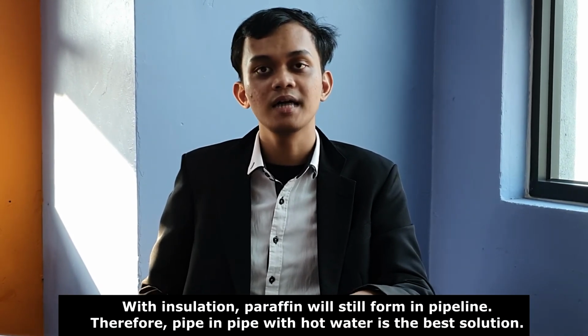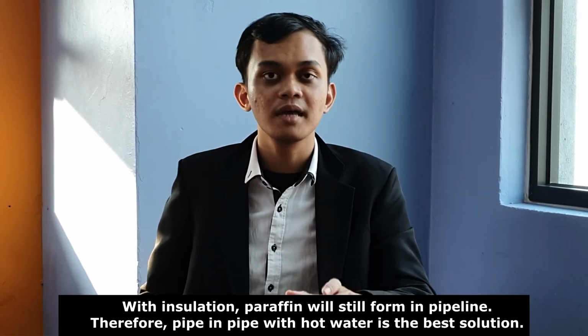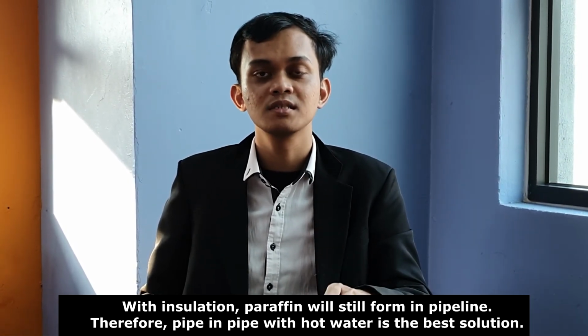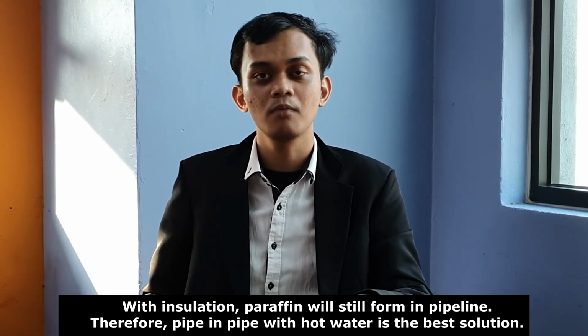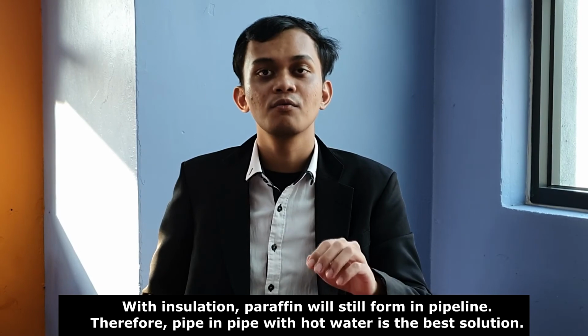So back to the insulated and buried pipe, the temperature drop is small. But for a 300 km pipeline, this is unacceptable as the paraffin will still manage to deposit. So to summarize, the best solution for our paraffin problem is still the pipe with hot water. In conclusion, for the past 12 weeks of study and simulation, the best solution for OnePetro Solution to approach this paraffin problem in Bach Ho Field, Vietnam is pipe with hot water.